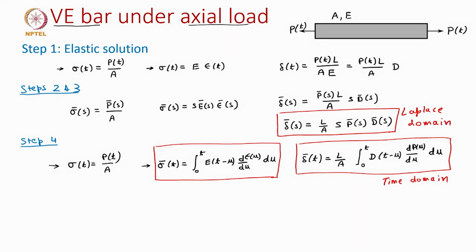Why I am trying to emphasize this is, depending on the kind of problems you are solving, it is not always true that you plug in or try solving in the time domain. Sometimes solving things in the Laplace domain will be easier. What I mean is, at the end we need to first substitute here the applied load P and the creep compliance D. Depending on the expression, sometimes it is easy to solve in the Laplace domain and sometimes it is easy to solve in the time domain. With a few examples we will see how we will use this equation, and we will also see instances when solving in the Laplace domain is easier than solving in the time domain.